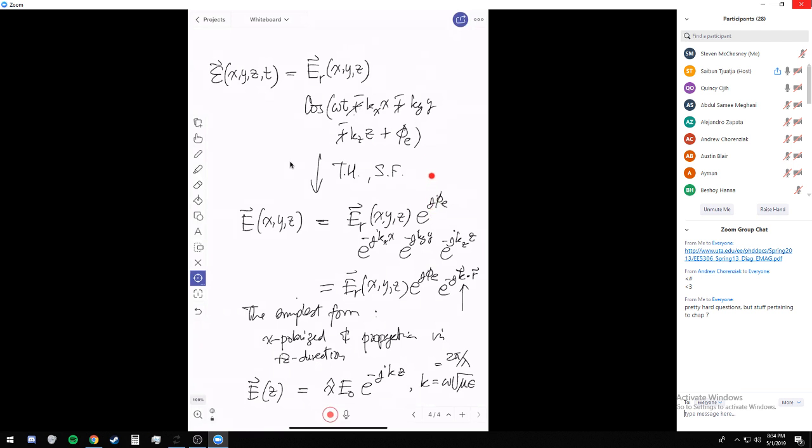Or, on the other hand, the reverse is true. I can give you the frequency. I can tell you, okay, I have a uniform plane wave propagating in the y direction and polarized in the z direction, and at the position y equal to 0, the amplitude is 10 volt per meter, for example.